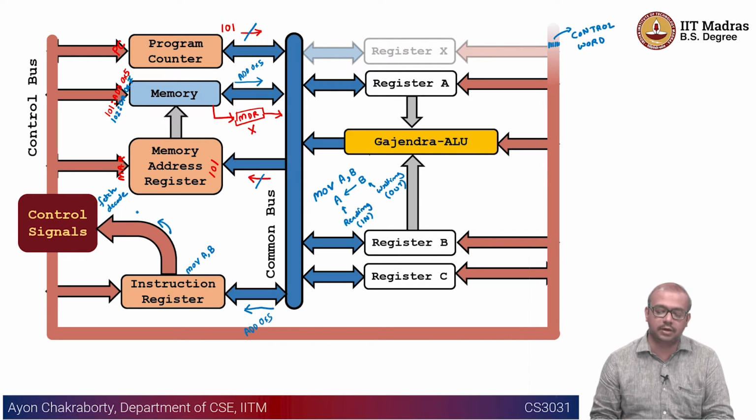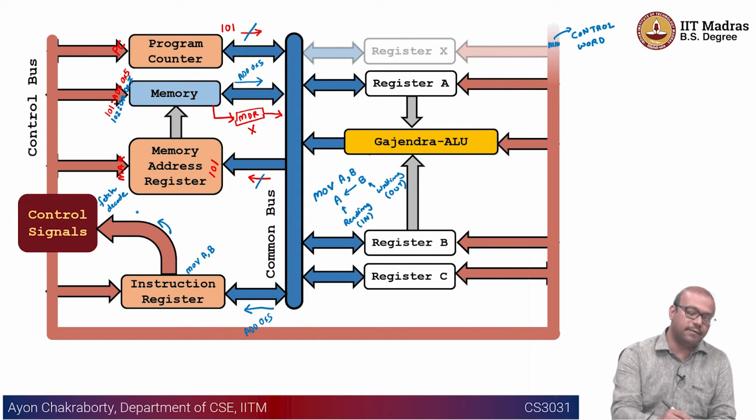And sometimes you also have to do operand decoding, meaning if you have an immediate instruction, let's say add 7, right? Or let's say you want to add the value of a particular register to the accumulator, depending on your instruction set architecture. In those cases, you also have to decode the specific operand that you are trying to use. Okay, so that is also important. So you need to decode the instruction as well as decode the operand. Okay, and after that you execute it.